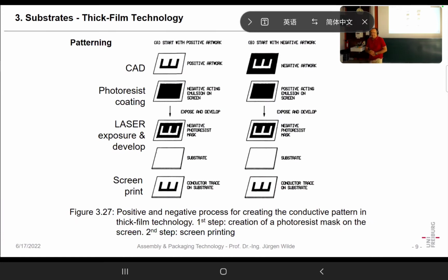Yeah. Okay. Especially in mass applications where you produce many. So the next thing, and that's important maybe to repeat, is how such layers are produced. First of all, they are printed, and typically it's screen printing. So that means you have a screen, that screen has openings, and you press a certain paste through the openings in that screen.